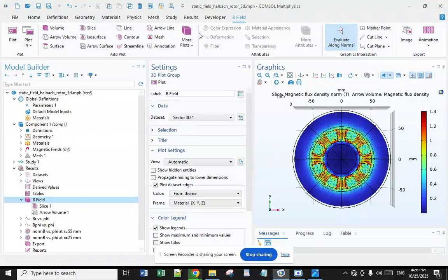In fact, any magnetization pattern where the components of magnetization are out of phase with each other will result in one-sided flux. The mathematical transform that shifts the phase of all components of some function is called a Hilbert transform. The components of the magnetization vector can therefore be any Hilbert transform pair, the simplest of which is as shown here.